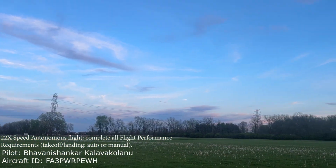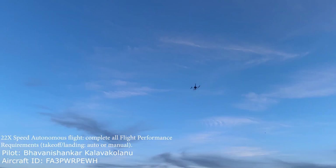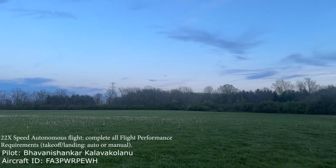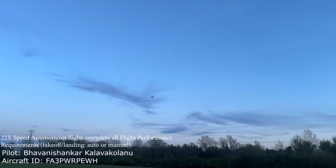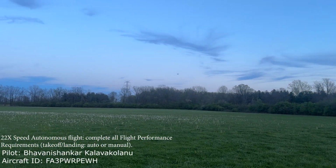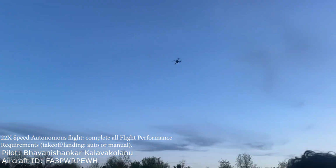For drone communication, we utilized the CHM30 for transmitting video and telemetry on the 1500 and 5825 MHz bands, with a 20 km range of telemetry and RTSP transmission to the Jetson for video. Despite noticeable video latency, it remains compatible with our camera. Additionally, we employed the Spectrum DSMX receiver operating at 2.4 GHz with the RadioMaster TX16's transmitter, using PPM data type and experiencing packet loss ranging from 1 to 5% during normal flight tests.